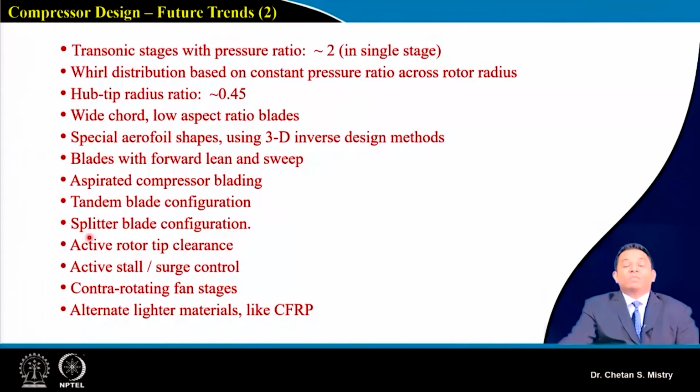Next is the splitter blade configuration. The splitter concept was adopted for the centrifugal compressor. Later on people realized this is very good in the sense of application for rotor design, mainly transonic rotor design.